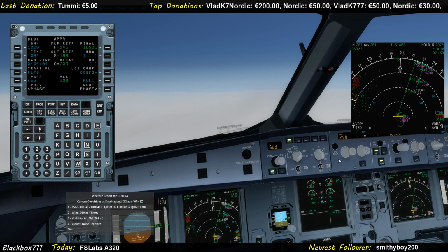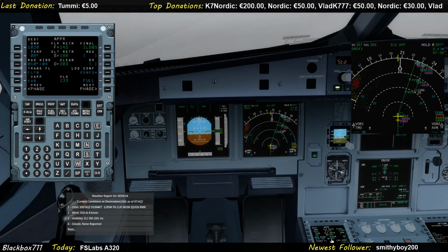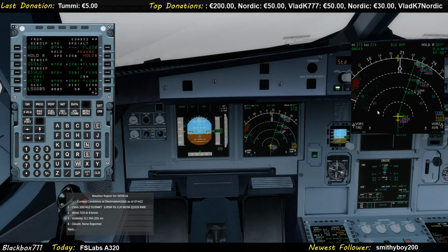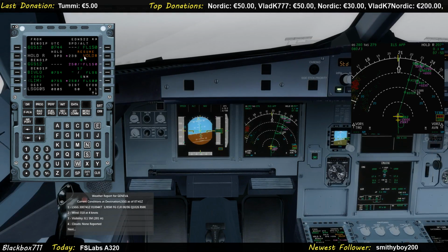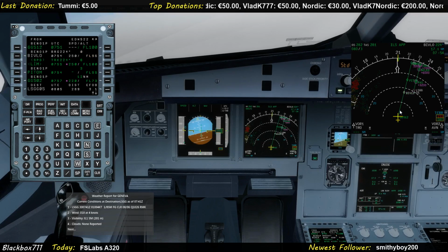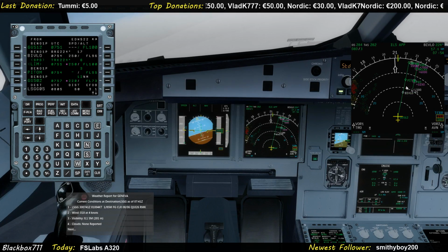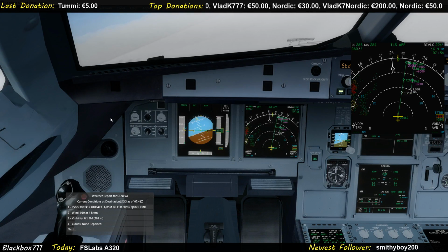And so now that we've pressed immediate exit on the FMS, you can also press resume hold again, but we're not going to do that. We're going to fly on the arrival route. So there we go. The holding disappears, and we continue on the arrival route.